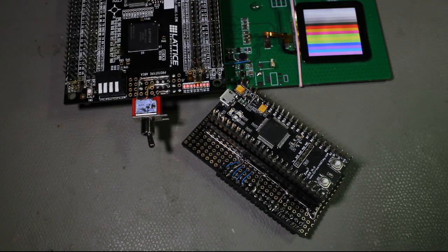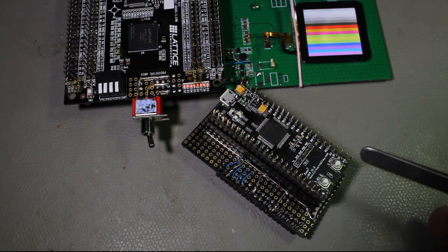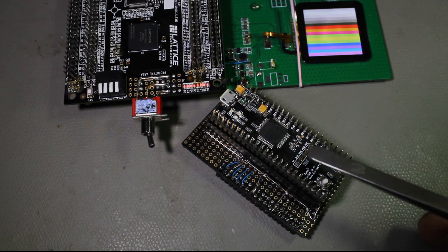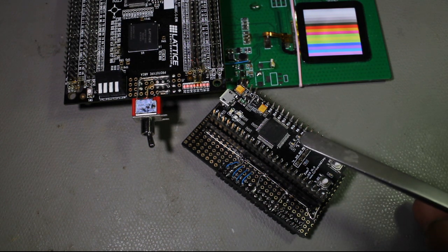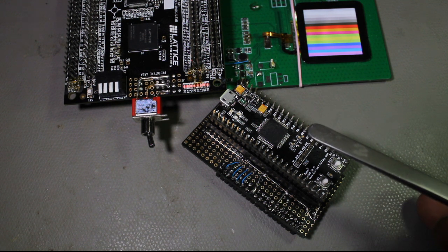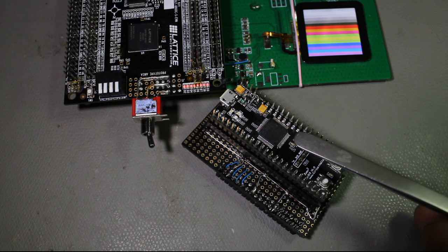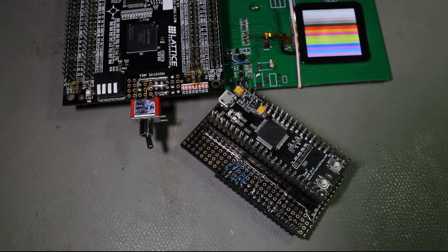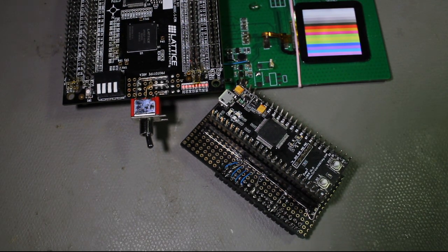As explained earlier, I have connected this whole FPGA setup to the PC over USB using a PIC32 microcontroller. I have previously made this little board. The nice thing about this board is the PIC32MZ2048EFM064 microcontroller. And the nice thing about this microcontroller is it has USB HS. It can achieve pretty high data rate for a microcontroller.